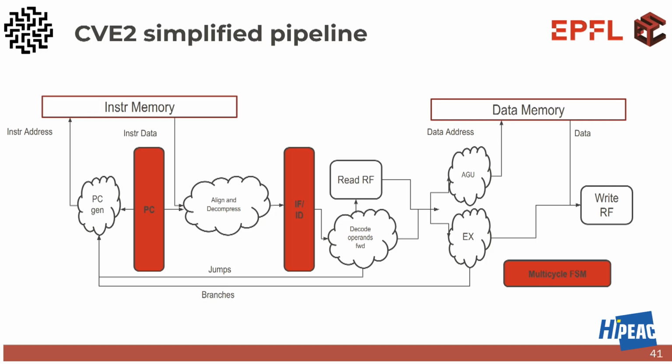Okay? Can I have data hazards in this pipeline? If any of you is familiar with data hazards, I guess, no? From computer architecture. Can an instruction in the ID stage depend on another instruction that is in which stage? X? I don't know. Right? But there's nothing. So there's no data hazard in this CPU. Amazing. We simplified a lot of multiplexers and a lot of control state machines. Good for my area and my number of gates. But I have a lot of structural hazards, yes.